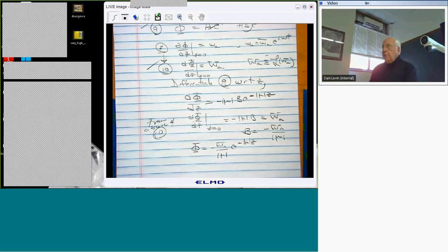Now I'm going to use Bernoulli's equation to compute P, the pressure, not the Laplace transform variable, but the perturbation pressure in terms of this, which is given by this, right? And of course, I have to assume simple harmonic motion for the pressure too, and I need to take the Laplace transform with respect to x of the Bernoulli equation.